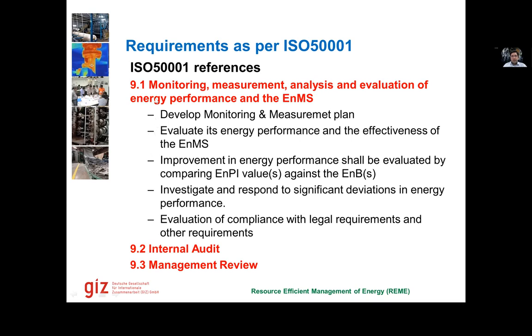If you look at ISO 50001, it requires monitoring in section 9. Section 9.1 says monitoring, measurement, analysis, and evaluation of energy performance and the energy management system, which requires you to develop a monitoring and measurement plan, and evaluate energy performance and effectiveness of the energy management system. Improvement in energy performance shall be evaluated by comparing energy performance indicators against the energy performance baselines. Then investigate and respond to significant deviations in energy performance. So if you have normalized ENPIs, then both these points get covered automatically.